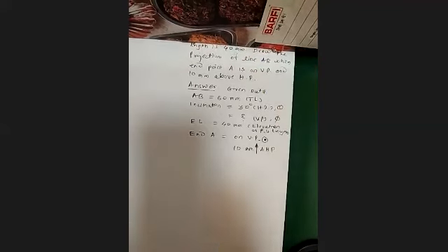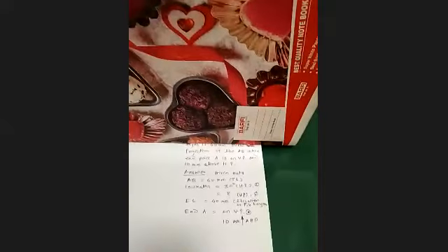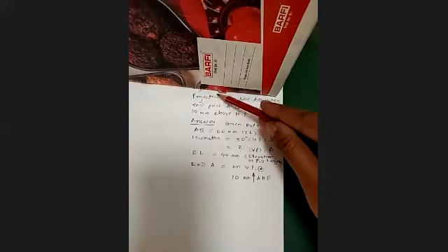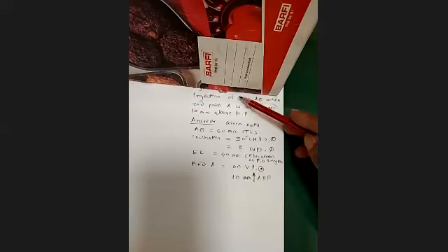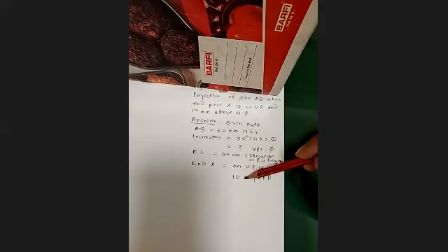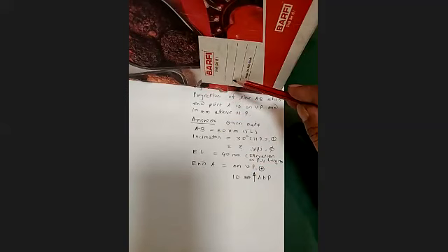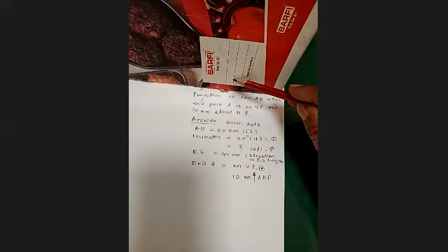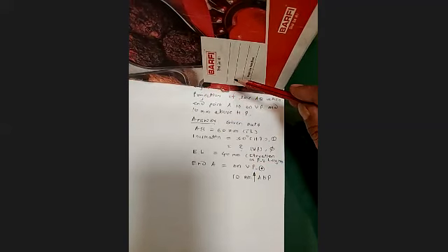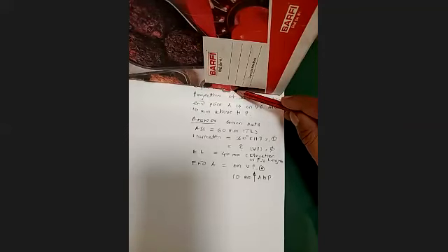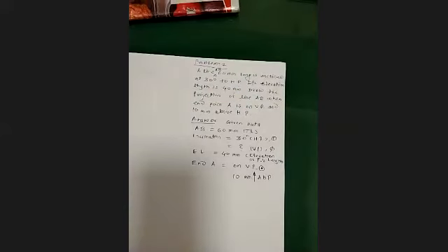Try to understand with this. See, this is the vertical plane and horizontal plane, and with reference to that, this is the XY line. This point is given on VP, and it is just 10 millimeter above HP. So A dash will be above HP by 10 millimeter, above XY line, but point A, the reference point of your top view, will go on the XY line. So we'll start with the solution step by step.